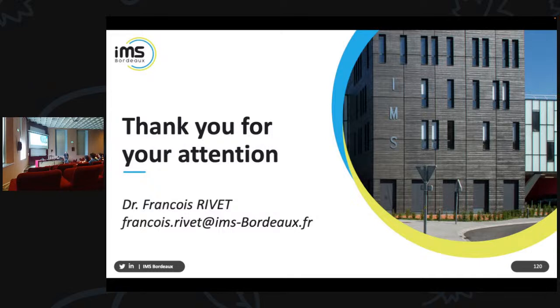Here you have a digital pre-distortion technique. Can I apply it to any PA? The answer is yes. You will apply it to different PAs finally. Also, the designer always tries to do his best to get the perfect S parameters, etc. Can I do a dirty design, and then the predistortion will do the rest of it? The answer is no. We still need good designers to make the first step to have a good design. I'm thinking about the output matching network or input matching network, etc. It has to be matched.